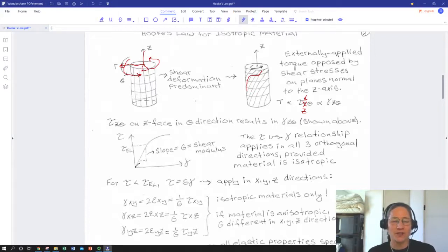So we get a shear stress versus strain curve that starts with a linear elastic region, reaches a yield point, and then heals over. The slope of this proportional elastic region of our shear stress-strain curve is called the shear modulus, and it goes by capital letter G. This is entirely analogous to our capital letter E elastic modulus. And in fact, we can relate it mathematically.